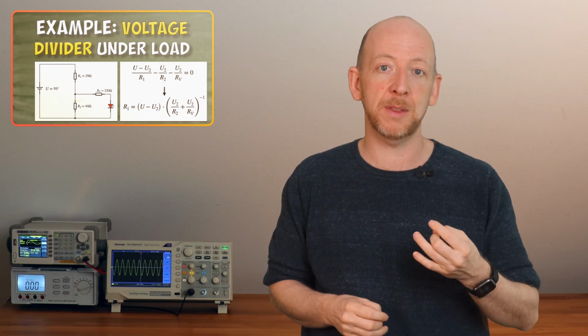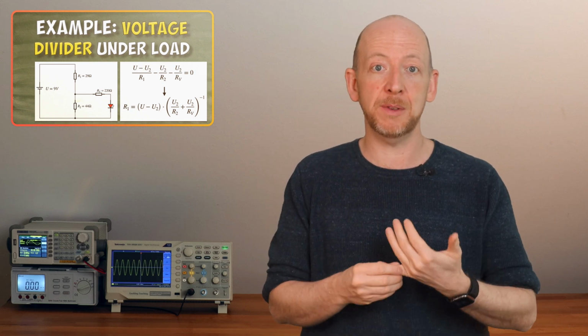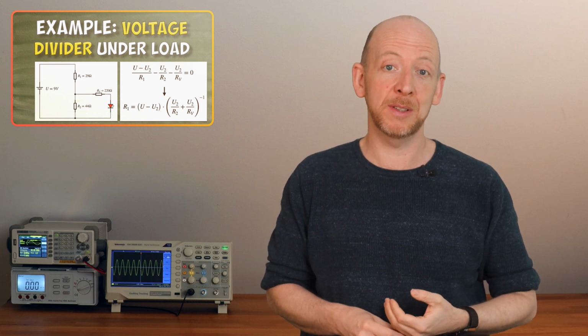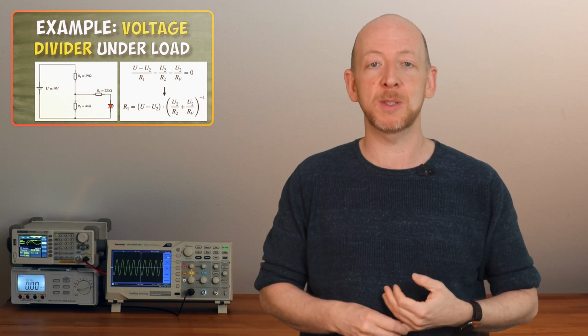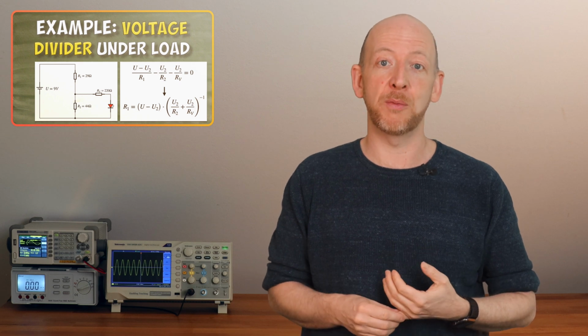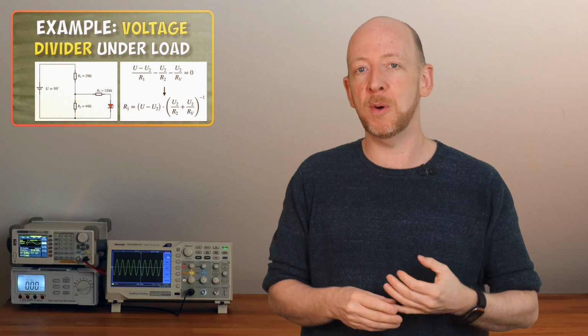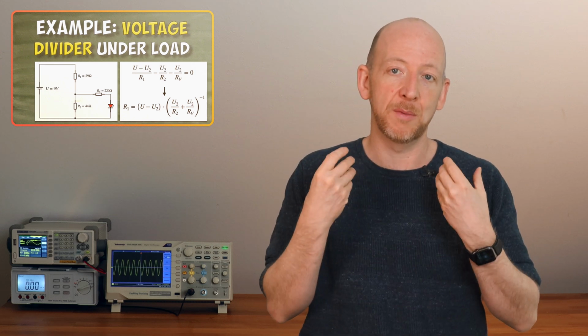And in order for this to work, the equation from the derivation of the loaded voltage divider must be adapted, and an empirical value taken from practice must be assumed for the ratio of load current to divider current. This is the key for solving this problem of supplying a constant voltage for the load you want to connect.